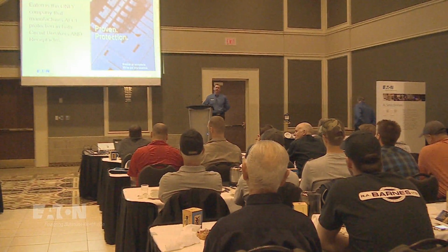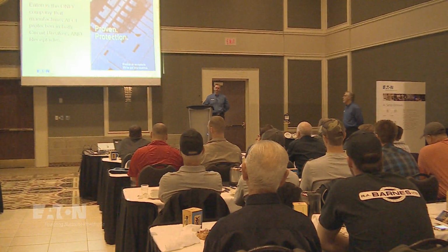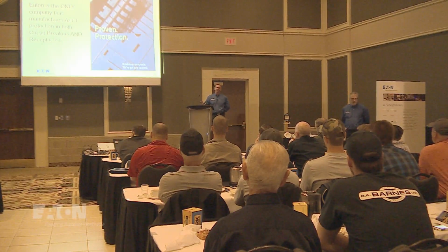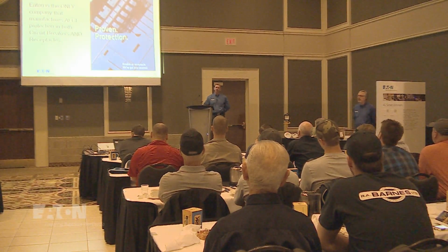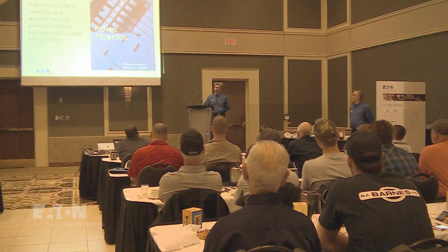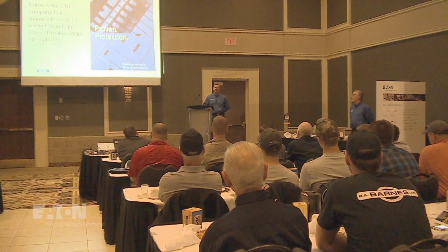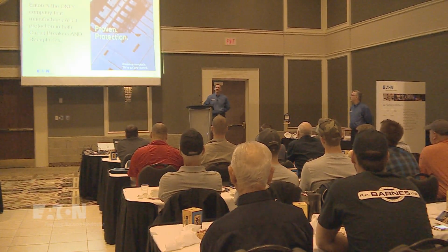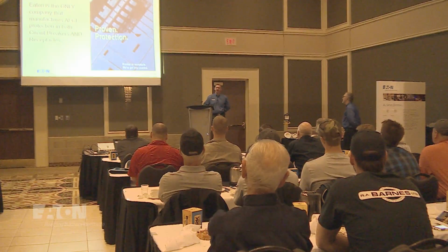Well, the question is whether the arc faults you're going to be using in bedrooms are different than the ones in the rest of the house. And the answer is actually no. The arc faults in the bedrooms are going to be the new type as well. They're going to be the combination AFCI. The code doesn't talk about bedrooms at all. It talks about all receptacles, and that includes the receptacles in the bedrooms. So going forward, those breakers will be combination AFCI instead of the branch circuit AFCI that they are now.